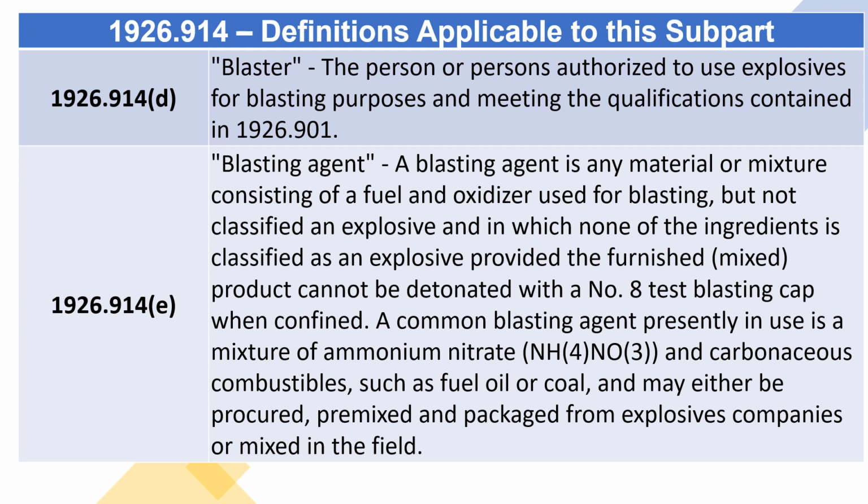1926.914(e). Blasting Agent. Blasting agent is any material or mixture consisting of a fuel and oxidizer used for blasting, but not classified an explosive and in which none of the ingredients is classified as an explosive, provided the furnished, mixed product cannot be detonated with a number 8 test blasting cap when confined. A common blasting agent presently in use is a mixture of ammonium nitrate and carbonaceous combustibles, such as fuel oil or coal, and may either be procured pre-mixed and packaged from explosives companies or mixed in the field.